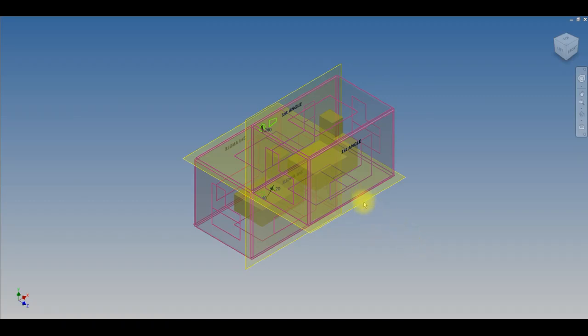We have to be able to present all the information we need on a 2-dimensional sheet of paper. We do not dimension 3-dimensional drawings. They are what's called pictorial, because you can see all the 3 dimensions, a height, a width and a depth. But when you draw them, it changes the lengths, just because of the nature of drawing isometrically and pictorially. The dimensions only go on 2-dimensional views. So we need to represent all of these correctly.